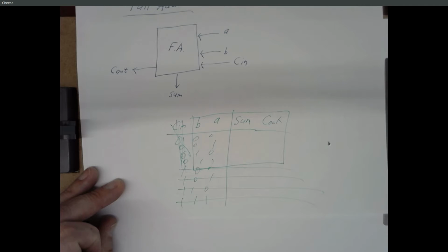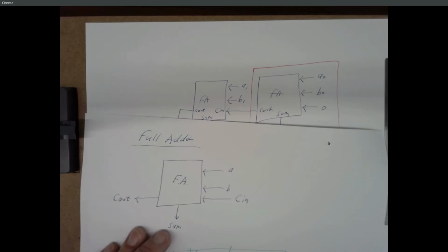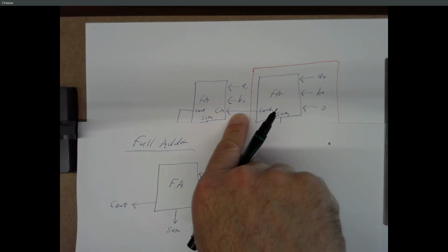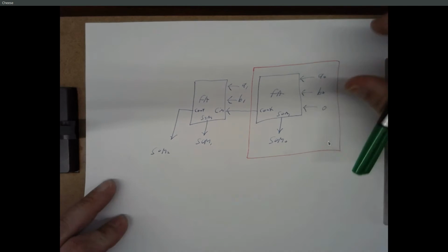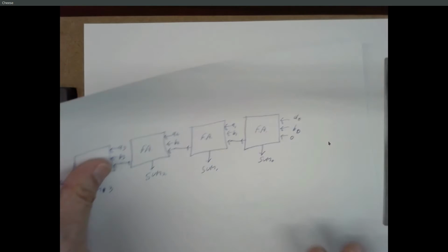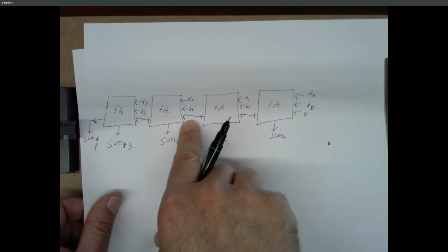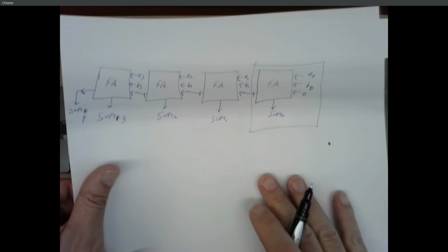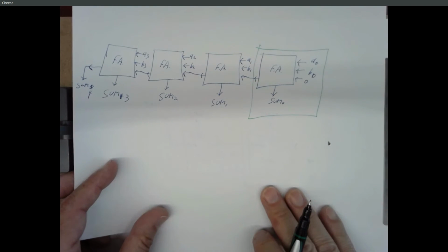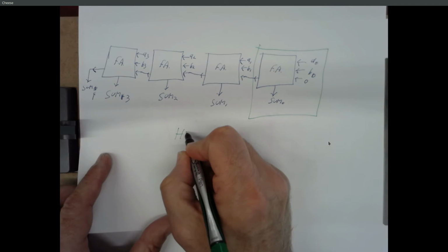That's a significantly simpler circuit. Now the second adder, that has to have 3 inputs because we've got a carry coming in. And if we build additional adders, that's got to have a carry in also. Right? All of these need to handle either a 0 or a 1 coming in, but this first one is special. So we can build a simpler circuit here, and this is something called a half adder.